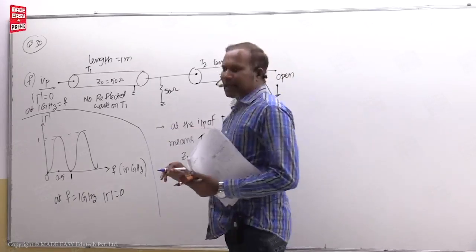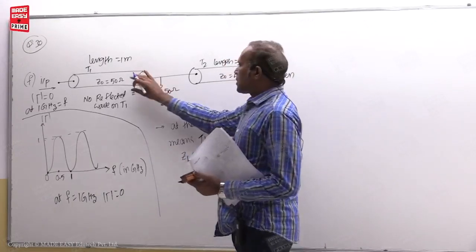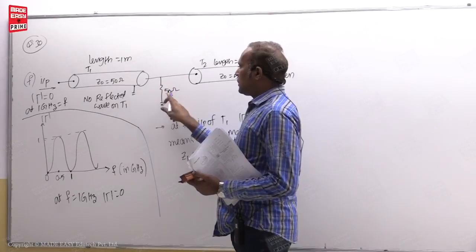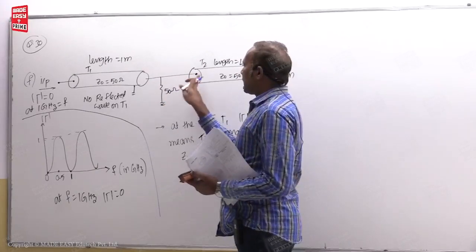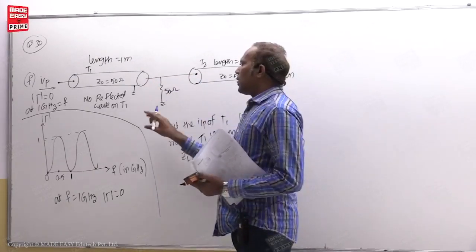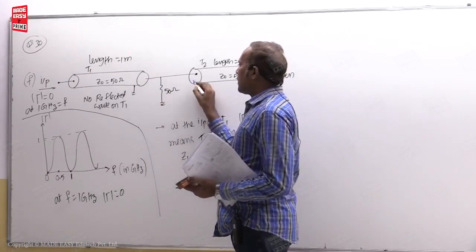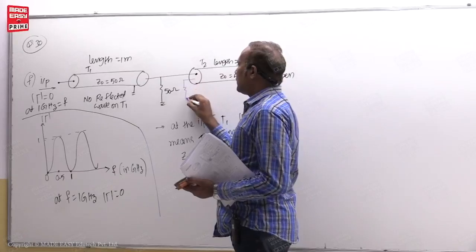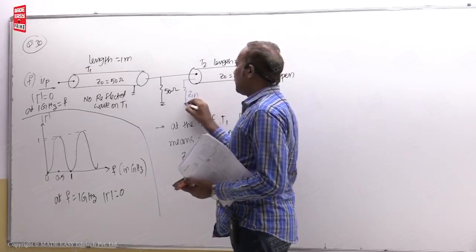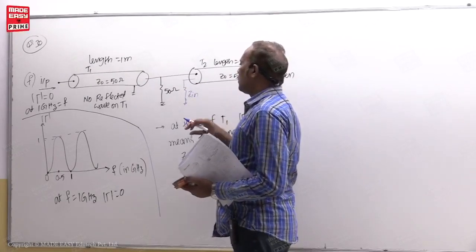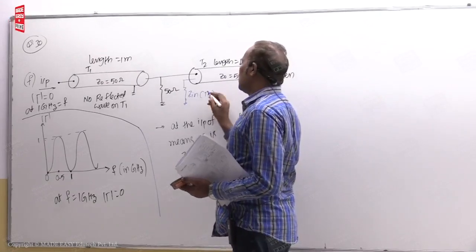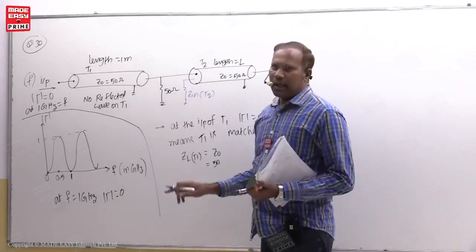Now it is like transistors. This is transistor 1, this is a 50 ohm connected load, then this is another transistor. Now for this, the load impedance is equal to the parallel combination of the input impedance of this T2 and 50, they are parallel, students.